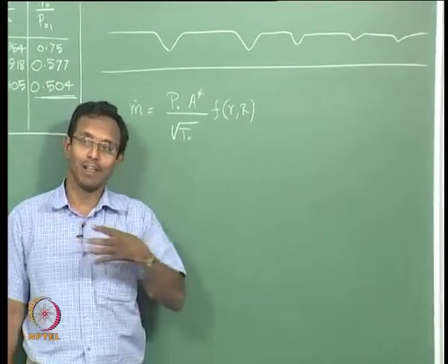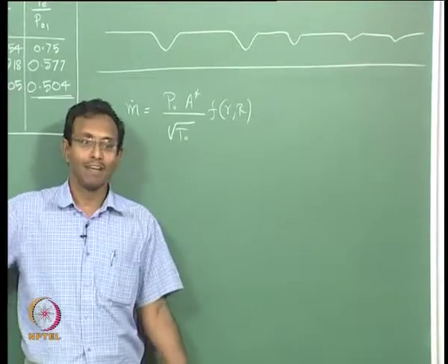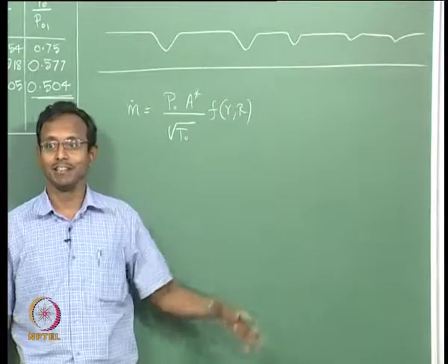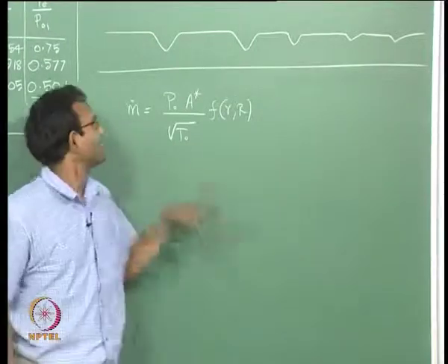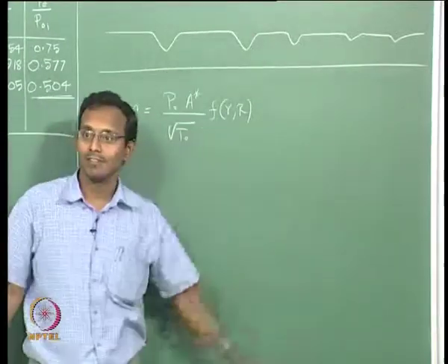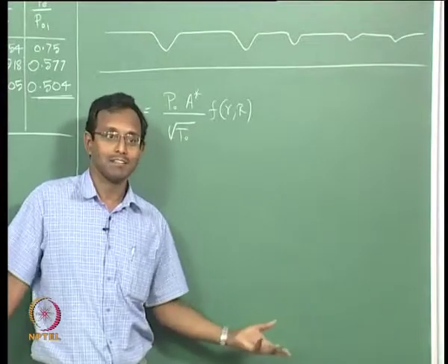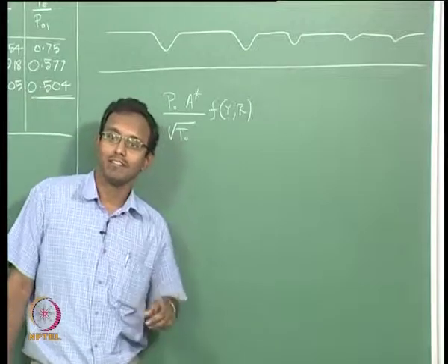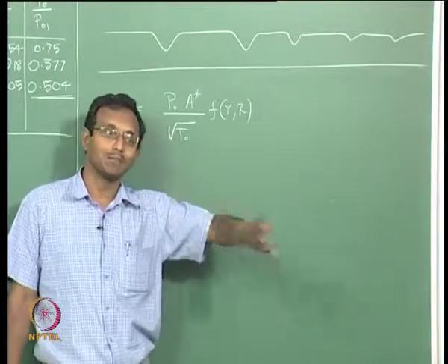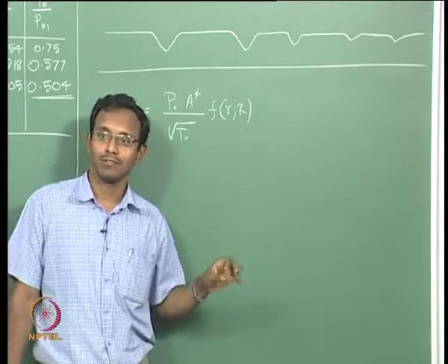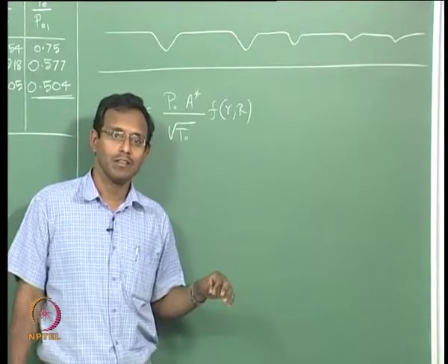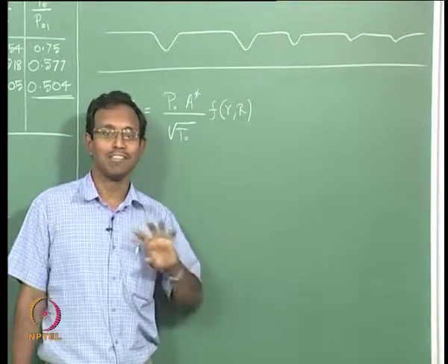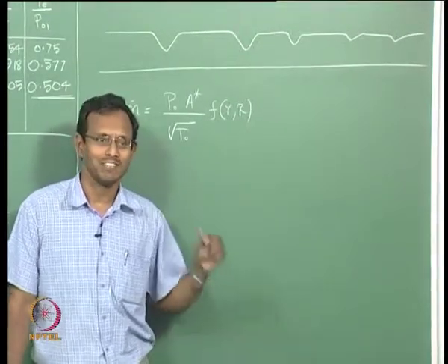If you are having a supply line of gas, you have a big tank and after a long distance, some flow facility, there will be so many valves in the middle, each valve is like a constriction in the flow. I can have several chokings. That is one particular setting where the flow is completely subsonic or just sonic, no supersonic. Even if you make a small mistake, one of them will become choked and everything else will become unchoked. That is a very critical situation.